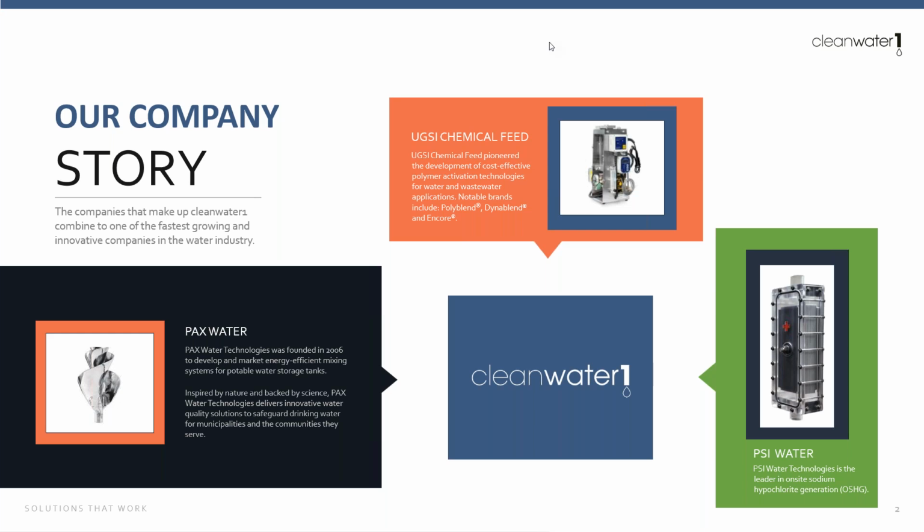We're doing a lot of different stuff these days. Out in the distribution system where we do our THM stripping, we also have some adjacent technologies, mixing for destratification, thermal destratification. We'll talk about that a little bit today. We also do a lot of residual boosting. So if you're experiencing low residuals out in the edges of your distribution system, that's another thing that we can help with. And in our company, we have a lot of deep expertise in distribution system water quality.